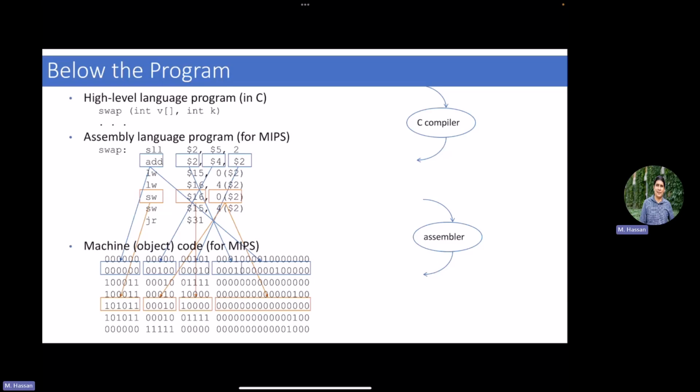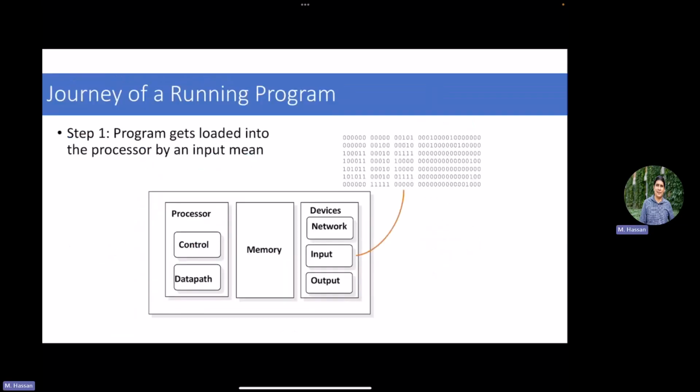So to know that this is an add, you need to look into these two fields together. But for the hardware to know this, it first looks into the opcode, because that's the constant part across all instructions. Once it determines it's, for example, all zeros, so it's part of arithmetic, then I go to the functionality and try to understand what's really happening, right? That's basically the mindset here.